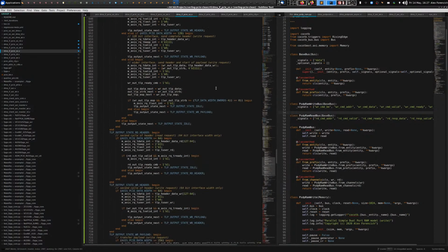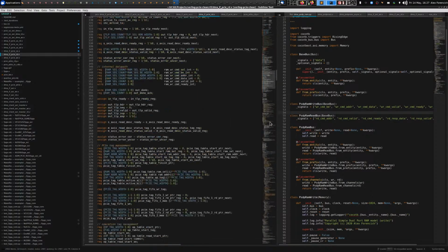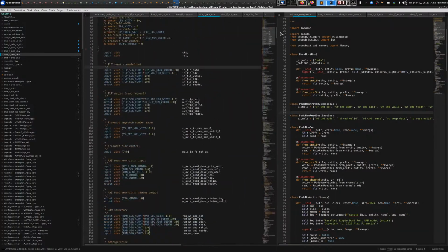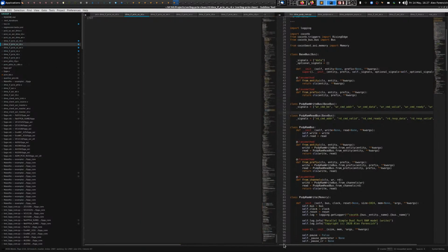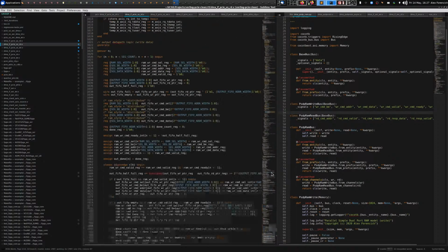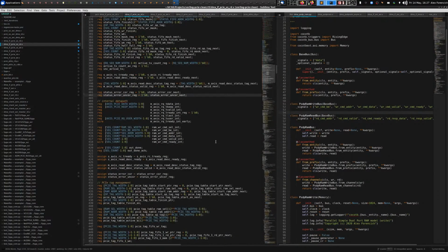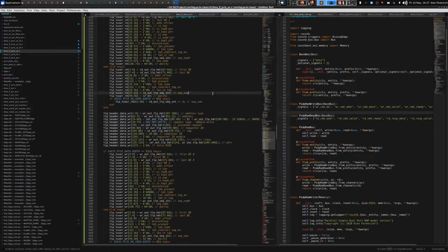It's not particularly complicated logic. And the other nice thing about separating this is it makes this core logic much simpler. And this is 1300 lines, right? This is the updated one. The previous one for UltraScale is 1700 lines. So you save a fair number of lines by making the more generic interface and by peeling off the device-specific interface code.